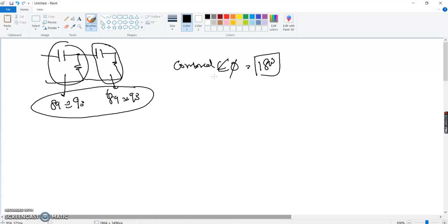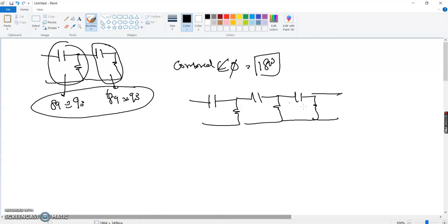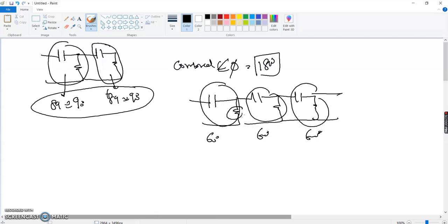Now, honestly, we discussed that we cannot reduce the value of R to such a low value. So the best possible way to construct a practical circuit is usually to have three cascaded stages. The first one would provide a phase shift of somewhat 60 degrees, the second another 60 degrees, and the third another 60 degrees. So we can have a manageable value of resistor. We know it was tangent inverse of XC over R, so we can manage that to get 60 degrees with some value of resistor. This is how the design of the circuit would look, with the capacitor and resistor combinations going over there.